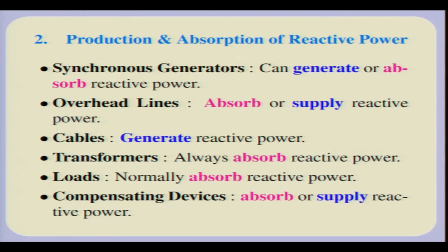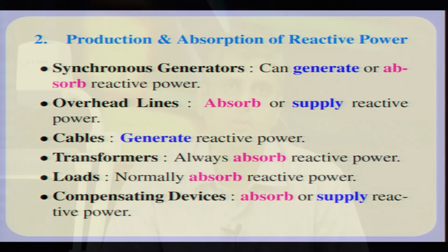Cables, normally the kind of cables we encounter in power systems, of lengths of a few tens of kilometers, generally generate reactive power. Of course, the question is, can a cable also absorb reactive power? The answer is yes, it can.